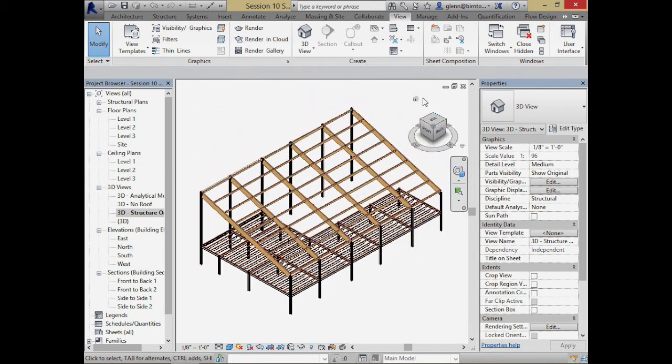We're basically saying that the structural framing here, the columns, the beams, is fully supporting the loads, at least the gravity loads. We'll talk about the lateral loads in just a minute. But all those gravity loads are really being carried down by the structural elements. We're not depending upon any of the walls to support those loads. And that's very common in a lot of commercial construction. It's the way that the Y2E2 building is constructed.